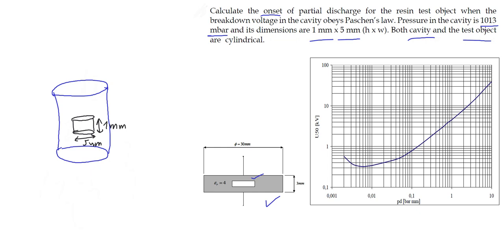Now if we draw a three capacitance model of this insulator, then it will look like this. We will have healthy insulation which is in parallel to the cavity, which can be modeled as capacitance Ca. Then in parallel to that, we have the cavity, and its capacitance can be labeled as Cc. So capacitance of the cavity, this one, Cc.